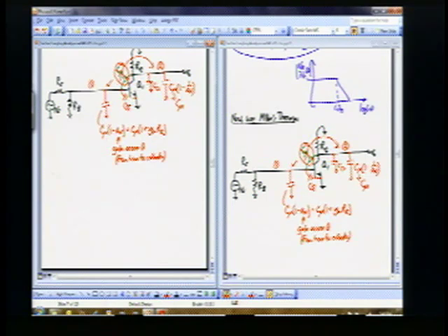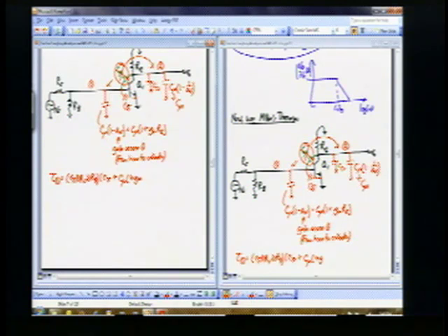So now I can just write directly that tau 1 is equal to all the resistance I see in shunt with that node, which we got before. That's just R pi parallel with RS parallel RB. But now times all the capacitance in shunt with that node, which is now C pi plus this Miller capacitance, C mu times 1 plus GM times that RC. And so that's now my new tau, but it's a total tau at node 1.